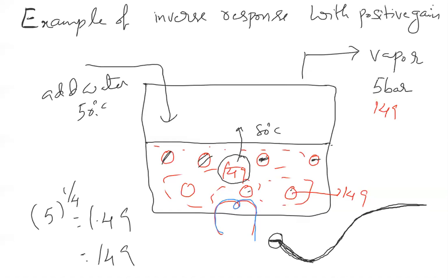Suppose level is 2 meters. Suppose my coil is here. My coil is sitting at, let's say, 0.5 meters. So the coil should not be exposed without water, that is the concept. Because this coil is carrying the flue gas which is hot at 1000 degrees. Suppose there is no medium which takes the heat, the coils will overheat and then they will spoil.